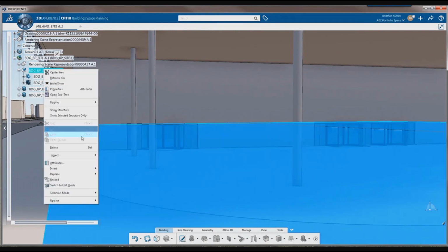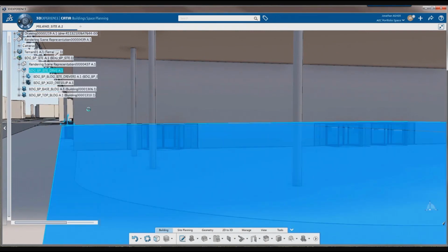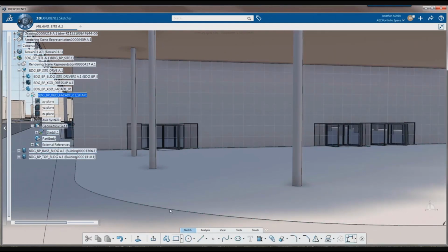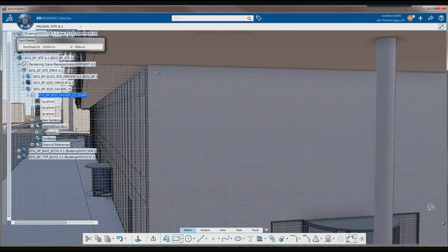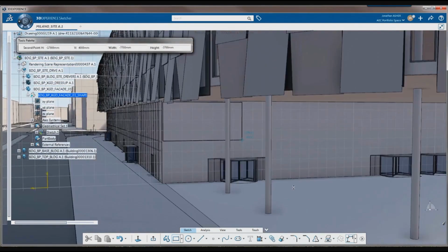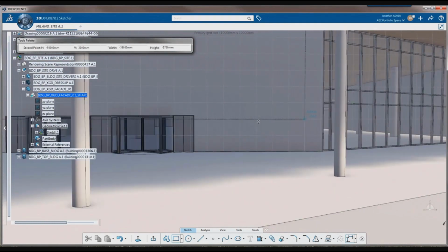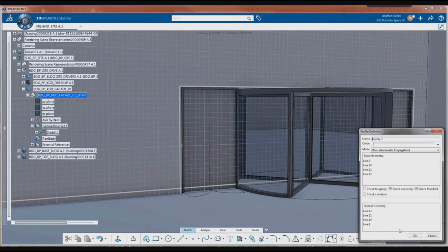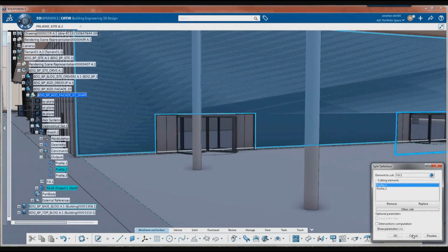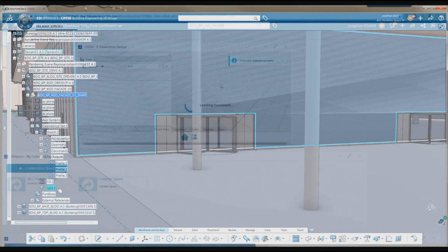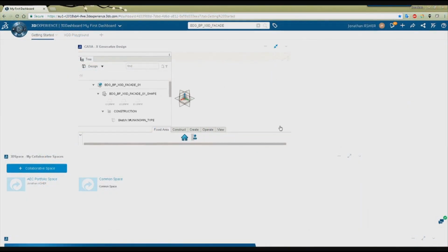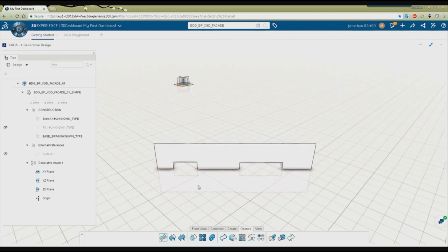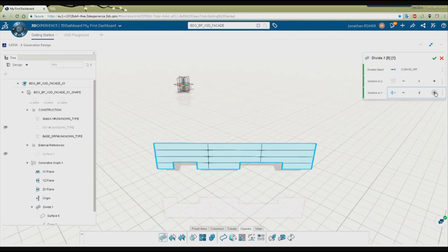This video is the collaborative feature wall video, where we're starting in CATIA on the rich client that you've installed on your machine. We're going to insert a new part into the model and use the CATIA sketcher to create a surface. So right now we're in the sketcher. We're going to make a quick surface. We're going to make a rectangle. We're going to output that profile curve. We're going to also create curves that define the boundaries of our doors. We'll make a surface. We'll split that surface. We'll save that file. And then we'll go to X Generative Design on the web, search our collaborative space, find that file, find that part, and open it in X Generative Design.